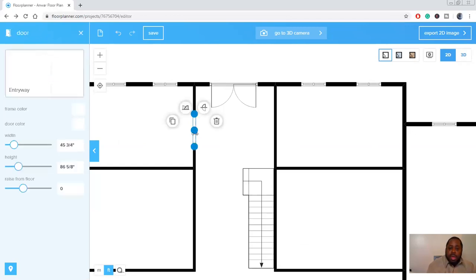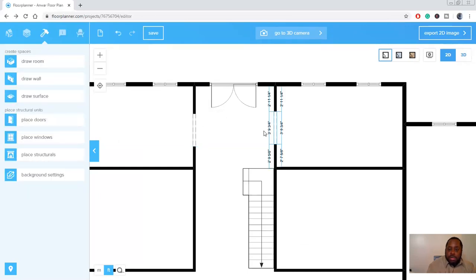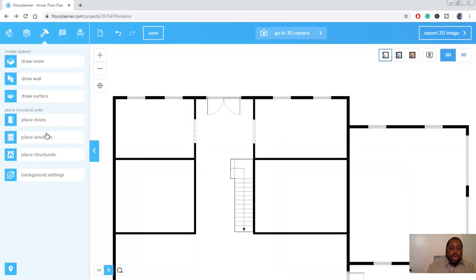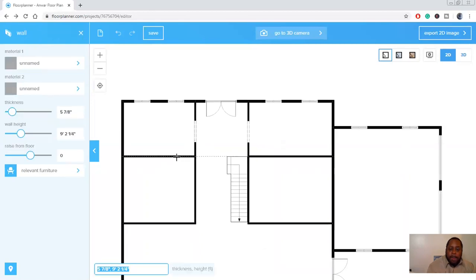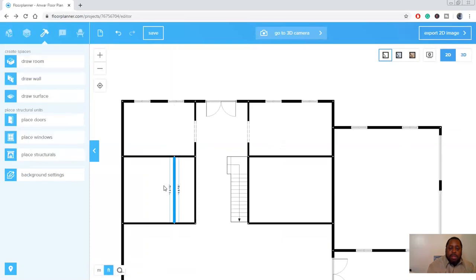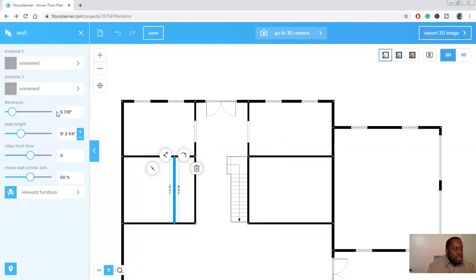So right now, I'm going to do copy, and then left click, copy. Pretty much it says duplicate. Place it over there. That's so that I can keep the same dimension that's on the drawing. Now what I want to do is create a wall right here. Come down, connect right here. I'm going to go back into it. Once again, 4 inches.